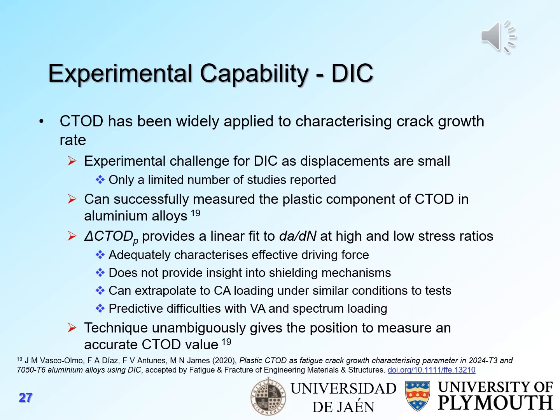DIC is also very useful for measuring crack tip opening displacement, although it's perhaps complex to resolve the very small scale displacements in crack tip opening. But crack tip opening displacement is a very useful parameter. It's been widely applied to characterizing fatigue crack growth rate and gives you an effective fatigue crack growth rate, but it doesn't tell you very much about crack physics. So as I note here, it's an experimental challenge for DIC as displacements are small.